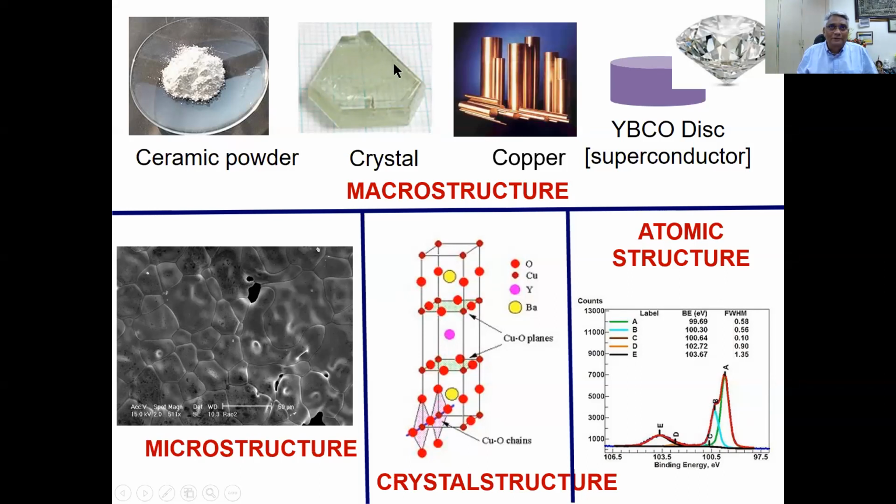If you take the 1 centimeter square area, or if this whole crystal, whole volume has to be declared a single crystal, that means from that point to all the other edges, this unit cell is arranged in a perfect periodic way without any misalignments, misorientations, etc. That is a crystal. To prove that, you need to go beyond X-ray crystallography. But crystallography is very essential. So a single crystal has how many grains? One grain, a single grain. Here it is a conglomeration of a large number of such small crystals, right?